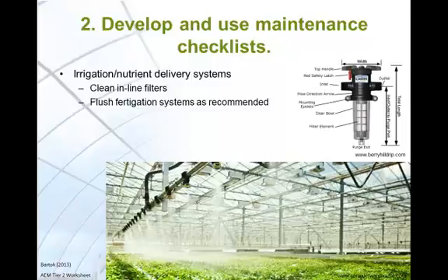Flush fertigation systems as recommended. For example, Netafim recommends a flush with clear water once a month. This will help to remove salt buildup. Sample emitters for proper delivery rate. This can be accomplished by dripping into measuring containers for a set amount of time and comparing the volume.